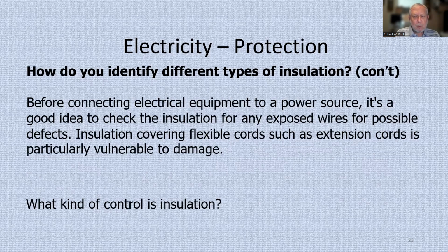Before connecting electrical equipment to a power source, it's a good idea to check the insulation for any exposed wires or possible defects. Insulation covering flexible cords, such as extension cords, is particularly vulnerable to damage.